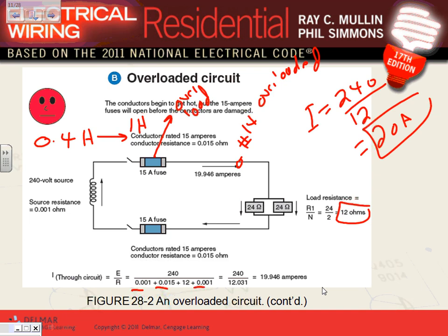It's a function of heat. Because the overload, what happens with the fuse, guys, the fuse element is going to be overheating, and when it reaches a point, it will melt the fuse element right here. There's a fuse element right in here that needs to be heated. So it takes time to heat this element. And that time is usually in minutes. In minutes all the way to an hour. It could take an hour for this one to trip. Okay? In minutes. Not in seconds, not in cycles, in minutes.